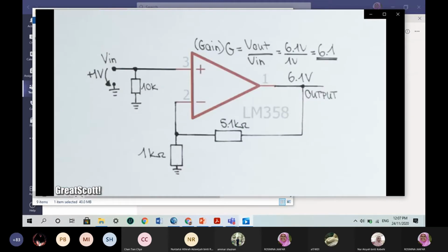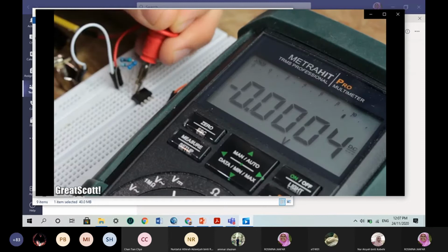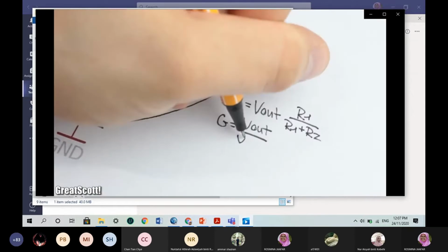But why? Well, the first golden rule of op-amps gives us the answer. The output of an op-amp will always attempt everything to keep the voltage difference between the inputs at 0 volts. That means there needs to be the same voltage drop across R1 as the input voltage Vin. If we now add the voltage divider formula to this and the fact that the gain is the output voltage divided by the input voltage, we finally get the classical formula for the gain of a non-inverting op-amp.